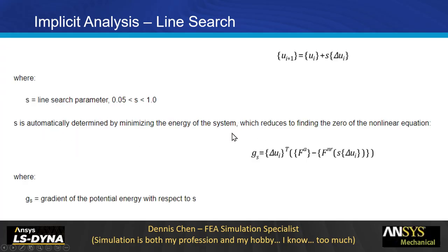So if the residual is increasing, this can be used to adjust the step internally within the iterations to help you get convergence faster. Think of it as a way to more intelligently get into convergence and save some computing power, some computational time.